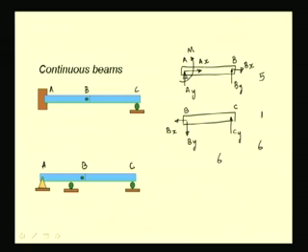Here we have a beam ABC which is pinned at A, supported by a roller at some point between A and B, and at C. Again we see that if we dismember or remove this beam from its support, it collapses. So, we dismember and construct the free body diagram. Let us draw the free body diagram for the beam AB.